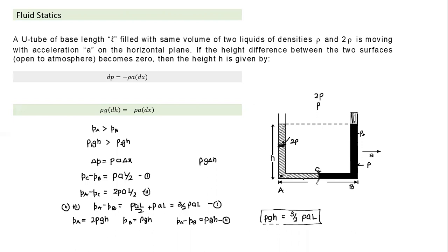They are different. So for any part of the liquid here, if I accelerate and take a small mass here, is this mass experiencing any net force? Of course, it has to experience a net force equal to ma. Which direction? This direction. How does this net force come about? Because the pressure force acting on its left-hand side is greater than the pressure force acting on the right-hand side. Is that clear now?